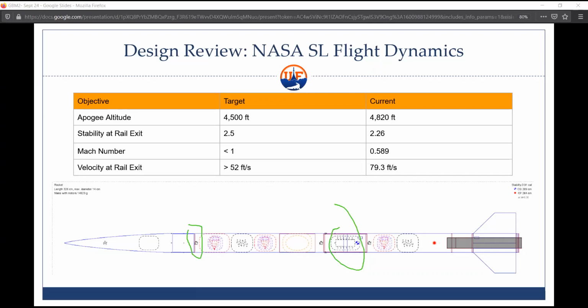But we also have to consider the failure mode. If the payload's in the back and doesn't deploy, our main parachute still comes out, so we don't have an issue. But if we have the payload in front and the main parachute behind it, then if our payload gets stuck, we have another missile in the ground. So definitely something else to consider as well.